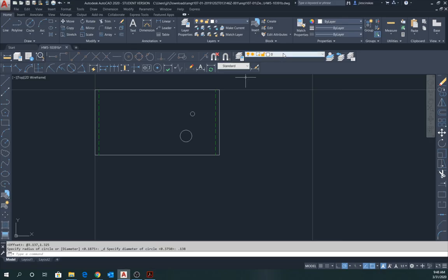We're going to go back to AutoCAD. We're going to choose center. And that bolt circle is going to be the same center as this circle. So we can just choose circle diameter, click on this center, and then now all we have to do is type in the diameter of that bolt circle. And the diameter of that bolt circle is 0.951. And that puts in the bolt circle.